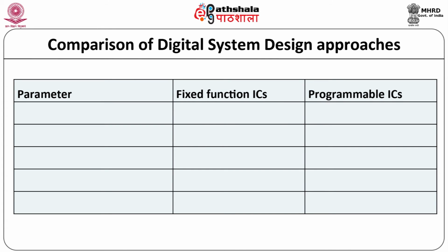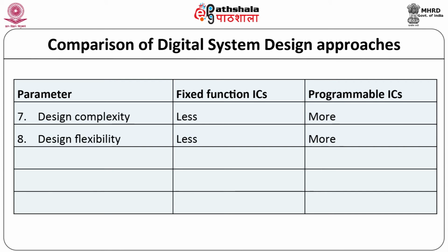Let us now talk about the remaining 5 parameters in the comparison. The fixed function IC based approach provides less complex design, whereas the programmable ICs approach provides more complexity. Fixed function ICs provide less design flexibility, whereas as we can program and change the design configuration, design flexibility is more. The time required for implementing the design using fixed function ICs is less.